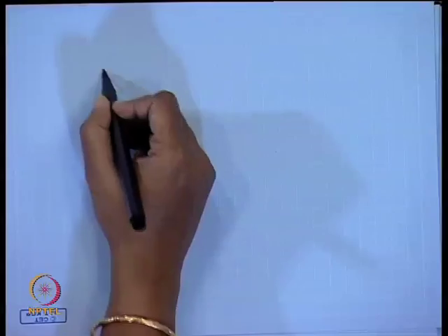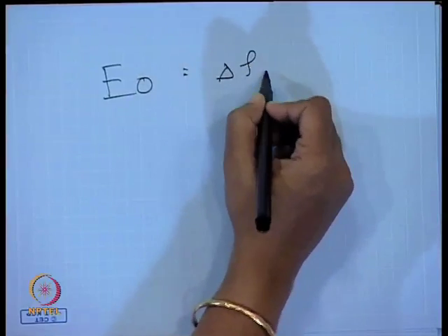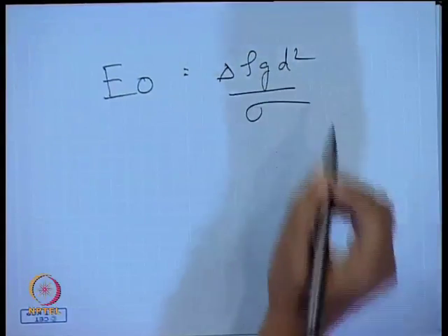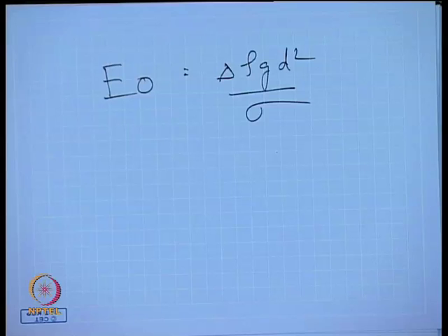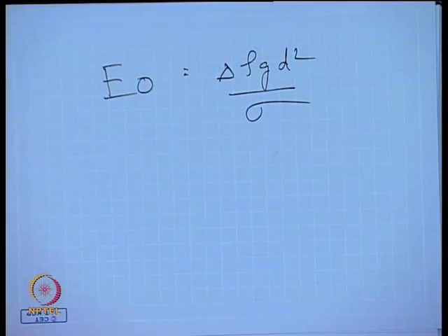Why? Because the in situ composition comes into being. And apart from this, other forces are also very important. For example, the Eötvös number, this is another very important group. I do not know whether you have heard about it. This is the ratio between the buoyancy force and the surface tension forces. For gas liquid cases, it is the surface tension of the liquid. For liquid liquid cases, it is usually sigma, the interfacial tension between the two liquids. This force becomes very important.